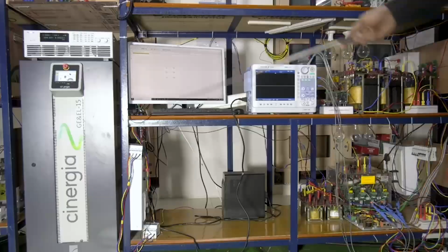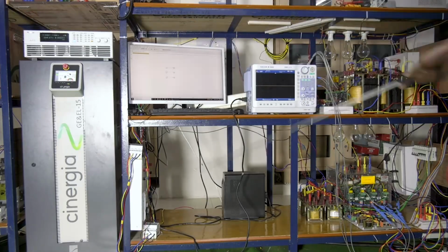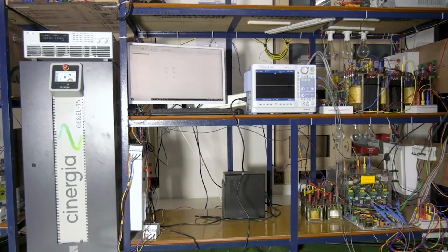Now, before going into the demonstration, let us have a look at the hardware connections. The PV emulator is connected to the DC input terminals of the IGBT stack. The AC output terminals, that is the RYB phases, are connected to the L filter. For each phase, we have connected two such inductor boxes in series to form a total inductance per phase of 6 millihenry. The other ends of the inductors are connected to the point of common coupling, PCC, formed by this MCB.